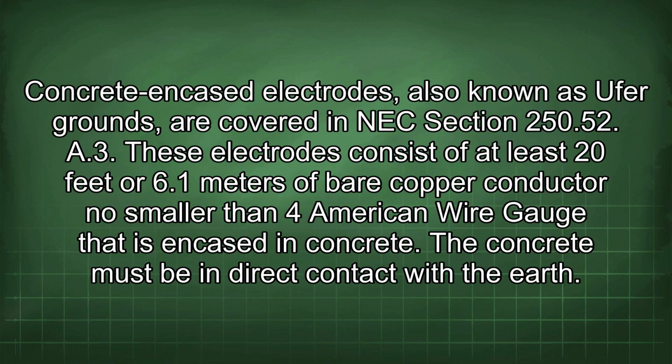Concrete encased electrodes, also known as Ufer grounds, are covered in NEC Section 250.52(A)(3).